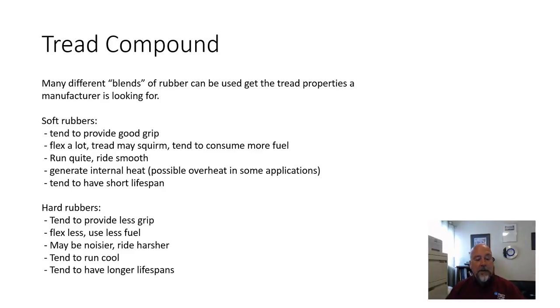Hard rubbers, they tend to provide less grip. They tend to slide easier on asphalt, and sometimes even worse on rainy asphalt. They flex less, so they tend to use less fuel. All right, it's the opposite of the soft rubber. They might be noisier or ride harsher. That does depend on the tread design, though. They tend to run cooler, again, because they're not flexing, they're not generating heat, and they tend to have longer lifespans.